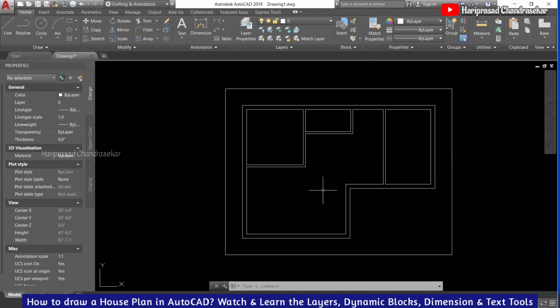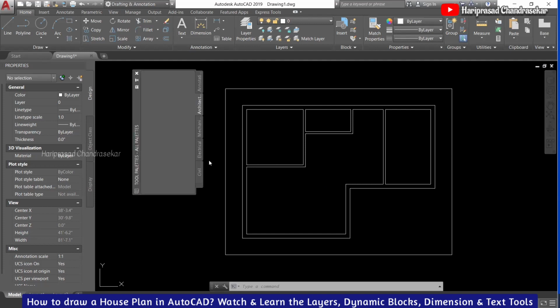Now I will go for Control 3. Control 3 is for the tool palette command. Tool palette, TP, enter, or Control 3, that you can take note of.